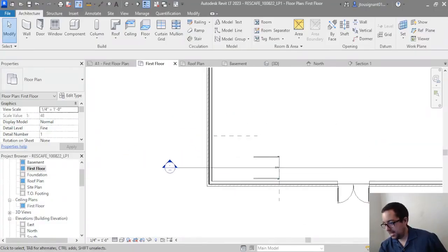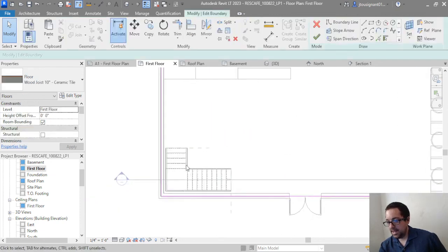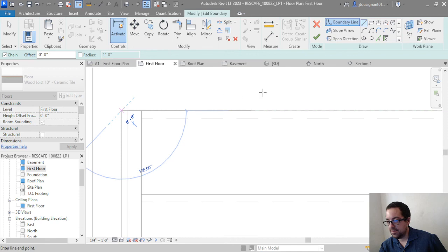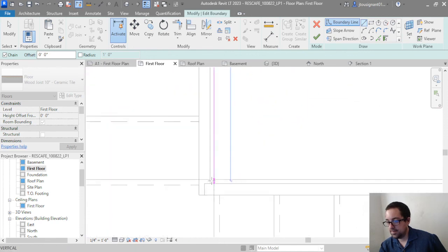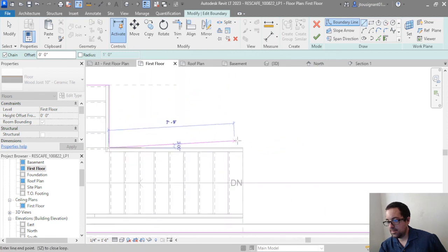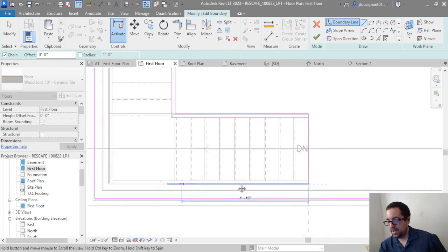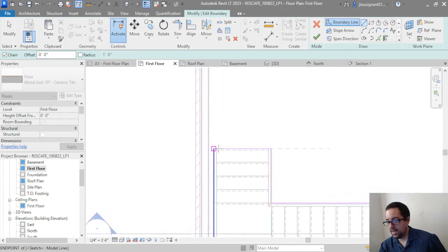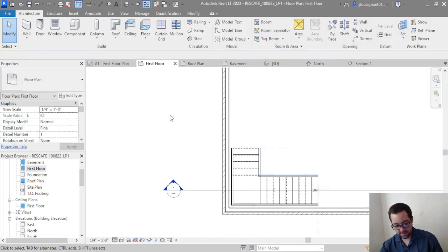And then I can select my first floor, call back to that face selection tool, and I could actually see the stairs below, so that's much easier. Now I'm just going to cut a hole the shape of these stairs. Could have done pick line, but that would have risked me having to do cleanup, and I don't feel like it, so I ain't gonna. And there, so now we've got some stairs, and those stairs have rails.